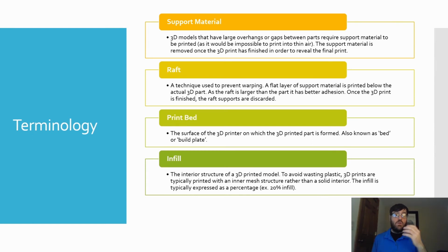So imagine you were 3D printing a baseball. If you tried to print the whole thing solid, it would take an incredible amount of time. If instead you kind of do a lattice structure inside and you use infill, you can support the outer layer, which is the only thing you'll actually see, and the inside can be much thinner on material. It can be kind of this lattice that just helps hold up the outer shell. That's what infill is. It helps to speed up prints, and it's also more economic in the use of your filament.